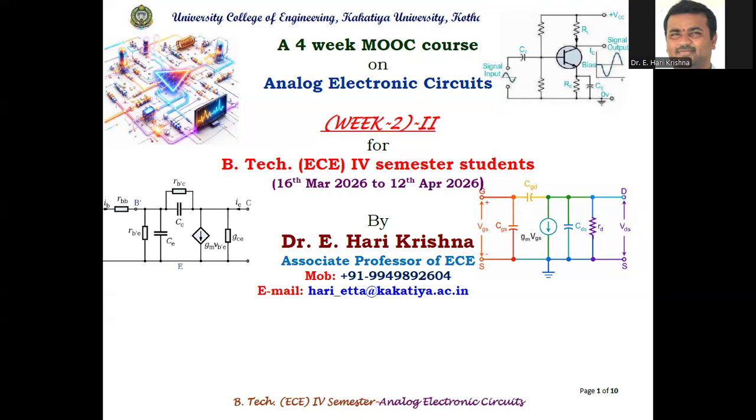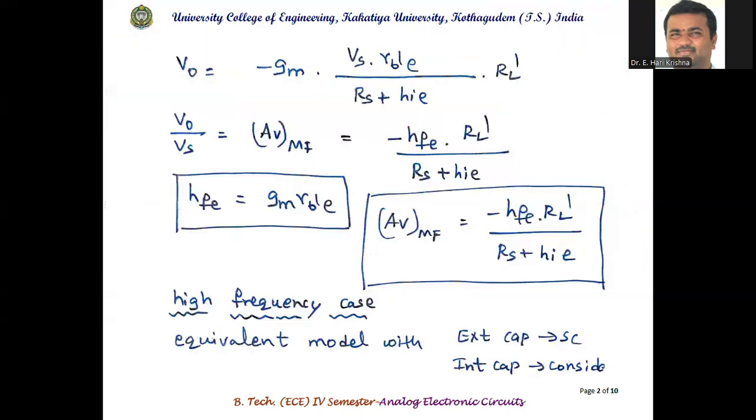Lecture 1 of week 2 discussed the mid-frequency analysis of the RC coupled BJT amplifier. Now, in this lecture, we'll see the high frequency analysis. As a continuation of the last session, in the high frequency case we need to see the effect of internal capacitors. So all external capacitors will be short circuited. We'll redraw the diagram of the last session considering only internal capacitors, short circuiting the external capacitors.